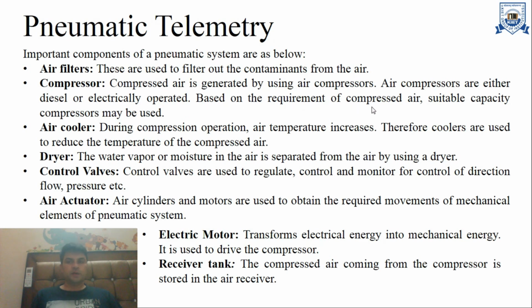Based on the requirement of compressed air, a suitable capacity compressor may be used; according to the process we can choose the compressor. Then the air cooler. During compression, air temperature increases, so coolers are used to reduce the temperature of compressed air. Then there are dryers. The water vapor and moisture in the air is separated from the air by using dryers.